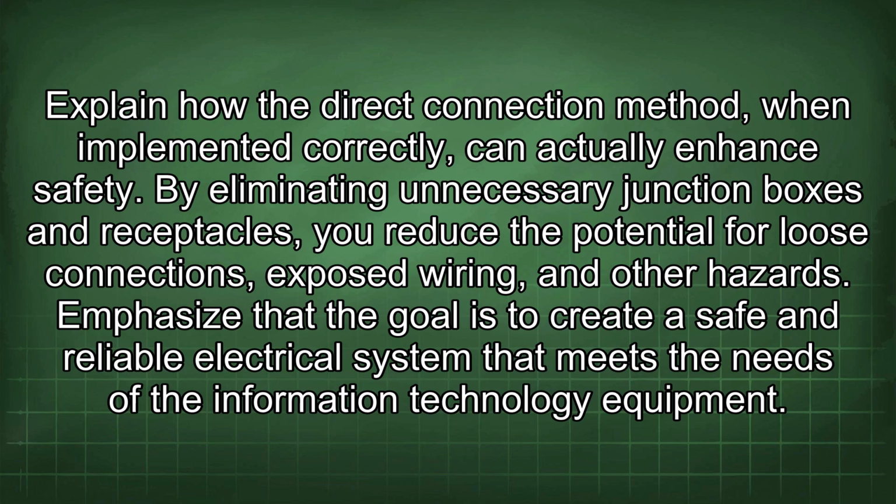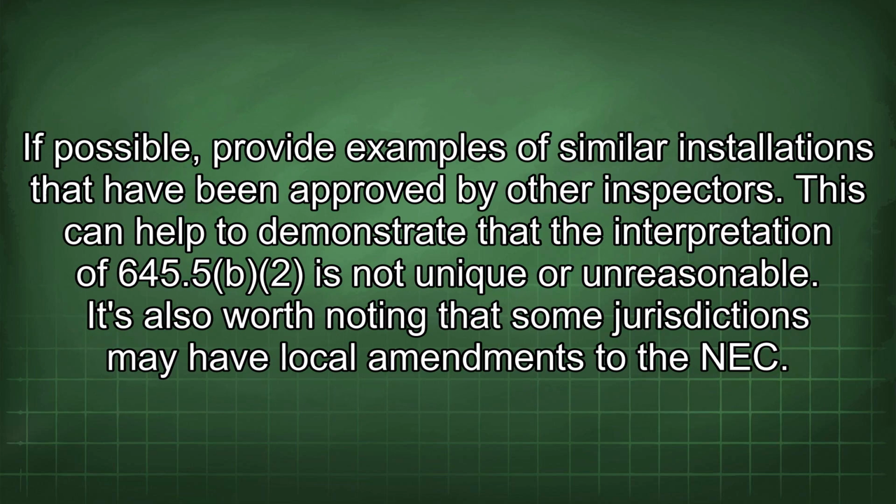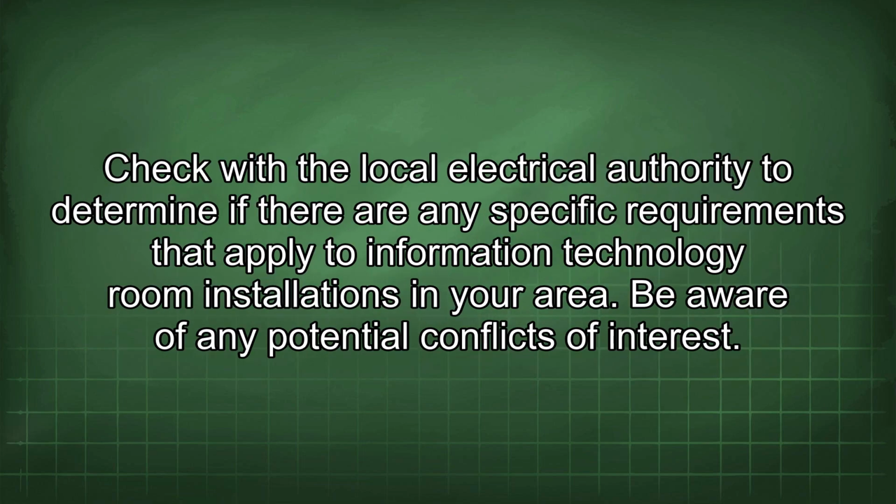Emphasize that the goal is to create a safe and reliable electrical system that meets the needs of the information technology equipment. If possible, provide examples of similar installations that have been approved by other inspectors. This can help to demonstrate that the interpretation of 645.5(D) is not unique or unreasonable. It's also worth noting that some jurisdictions may have local amendments to the NEC. Check with the local electrical authority to determine if there are any specific requirements that apply to information technology room